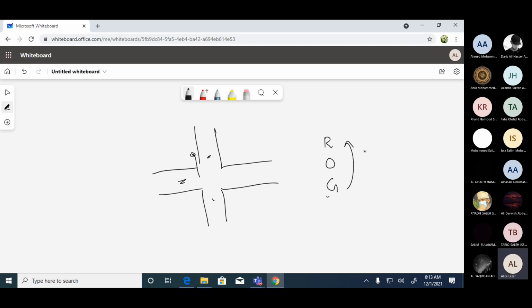Now, I know there are some cities where some traffic signals have been made smart. You must have seen a lot of examples. What are those smart traffic signals? They will have a load cell. You know the strain gauge, no? They will have a load sensor on the road. And the moment this load sensor is giving a signal that there is no car, the traffic signal is going to allow the car in the opposite road to move. Now that's a smart one, that's a closed loop one. But the usual ones that we see on roads are the open loop traffic systems, where the light is changing according to time and allowing the traffic to move.